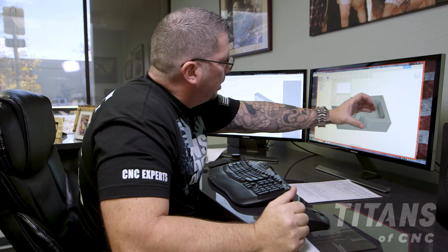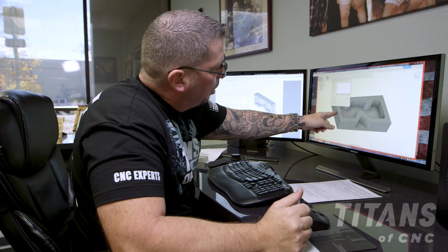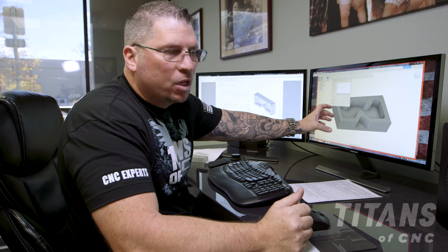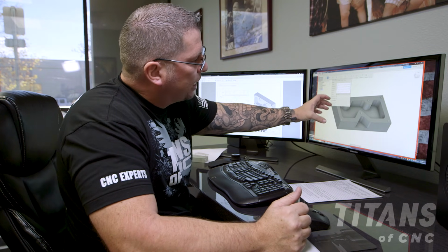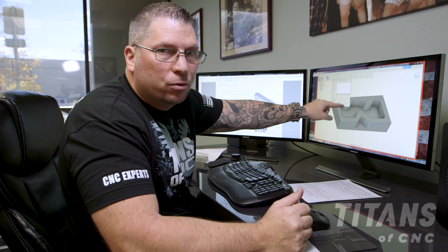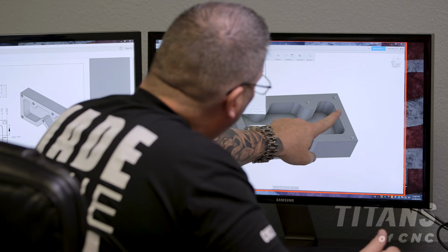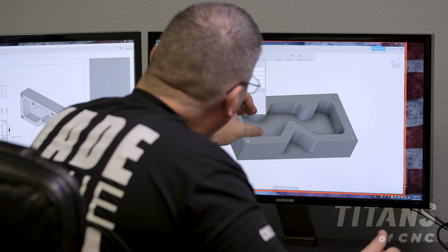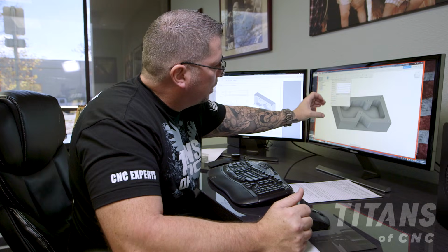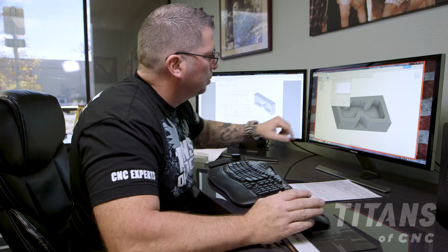But once it gets to the edge, and it's center of the tool to center of the edge, it's going to stop. But if it stops or starts arcing out, it could leave a line right there. The surface finish here will be different than how it started over here. So what I'm going to do is I'm actually going to have it come off the part until the entire tool has disengaged the material.